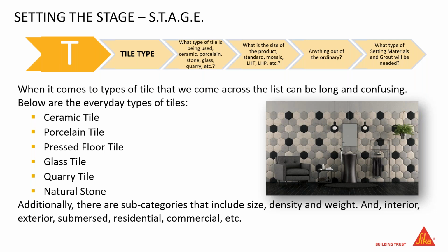So keeping that in mind, as a manufacturer, we need to manufacture products that work with those. As an installer, your installation techniques might change a little bit. The mortars that you're using definitely can change a little bit. We may not be using a thin set mortar for a large format tile. We all know why that reason is, but deciding on what type of tile you're presented with really plays a big picture in choosing the correct mortar for that application. So type of tile in that stage acronym is pretty important to help us kind of dive down to see what we're going to need.